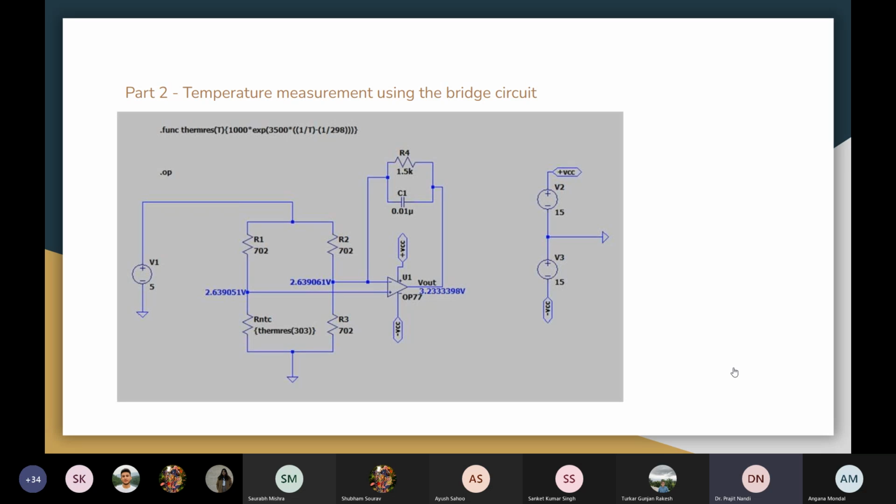But the point is we do not put discrete components to take care of noise. Care is taken inside, for example in the amplifier, through the choice of resistor values, the biasing current, or the device sizes. So the capacitor is actually placed for stability reasons.